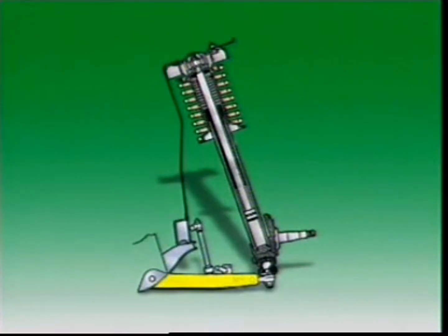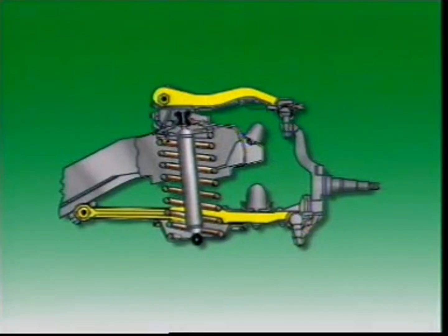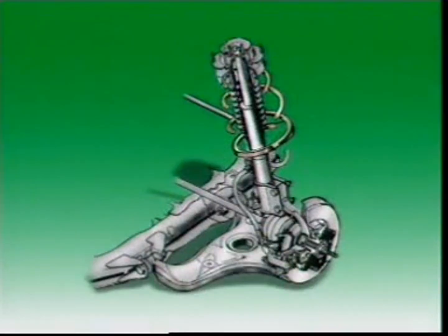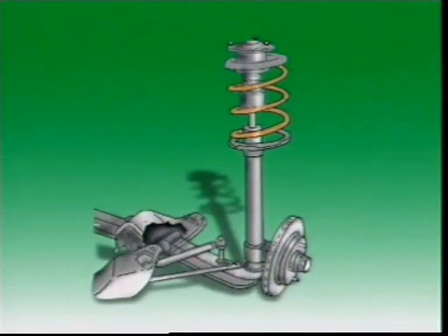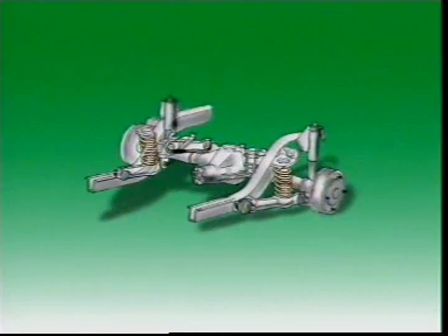The front suspension can have 1 or 2 control arms. Parallel link front suspensions have 2 control arms. Vehicles with strut-type front suspension have only 1 arm. It can be a wishbone shape with 2 fulcrum mounting points or straight with single fulcrum. The inner end of the control arm is pushed to the vehicle body, and the outer end uses a ball joint to allow changes in the steering angle for turning.